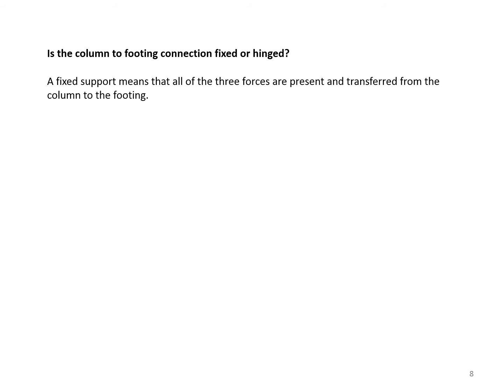A question is: is the column to footing connection fixed or hinged? A fixed support means that all the three forces are present and transferred from the column to the footing. A hinge support means that only the axial load is transferred to the footing.